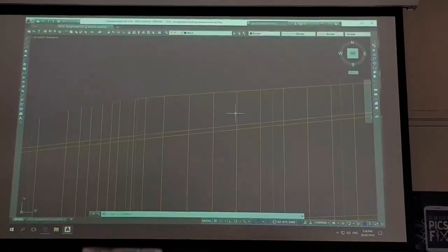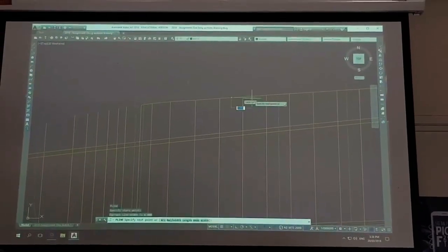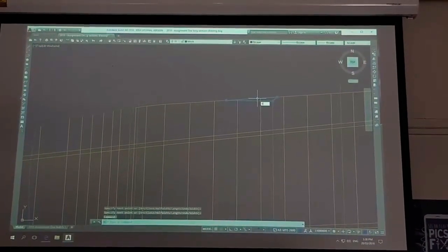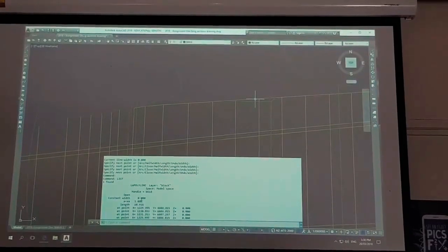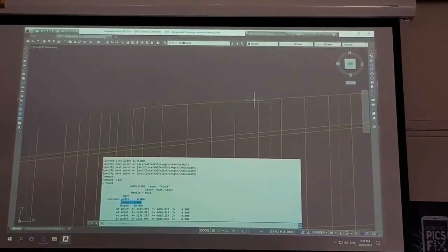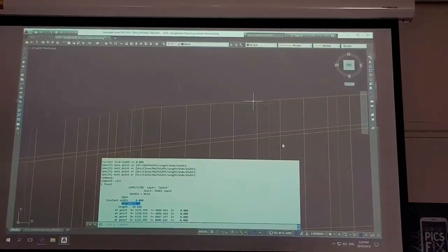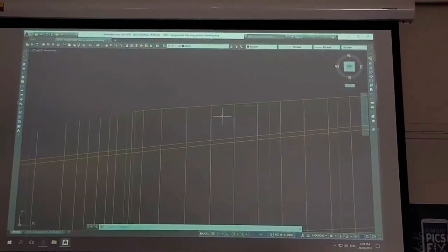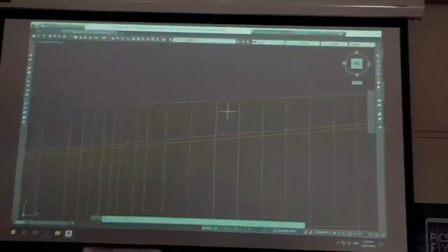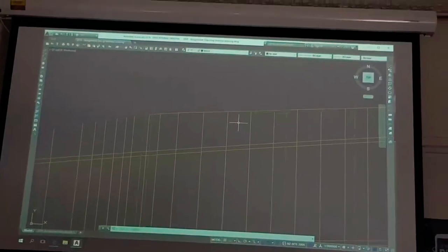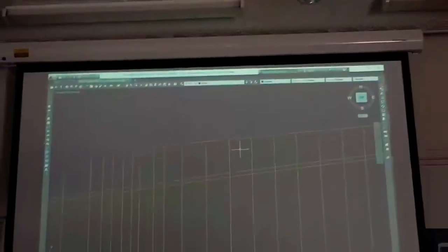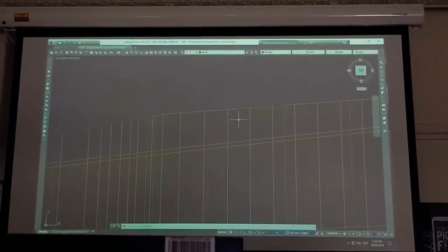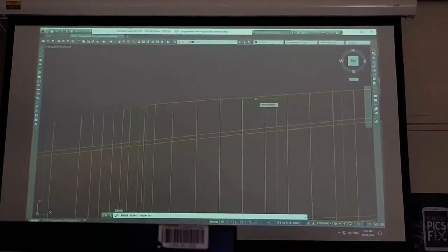This is a time when you can actually draw a P line around here, and you can click on it and go list, and you'll notice it gives you the area, which means you can give the area of cut versus the area of fill. Do not be confused, it is not a volume, it's an area only. But it is a very good indication that early on we think there's going to be quite a bit too much fill. So if you're looking at notes, there's some gold there.